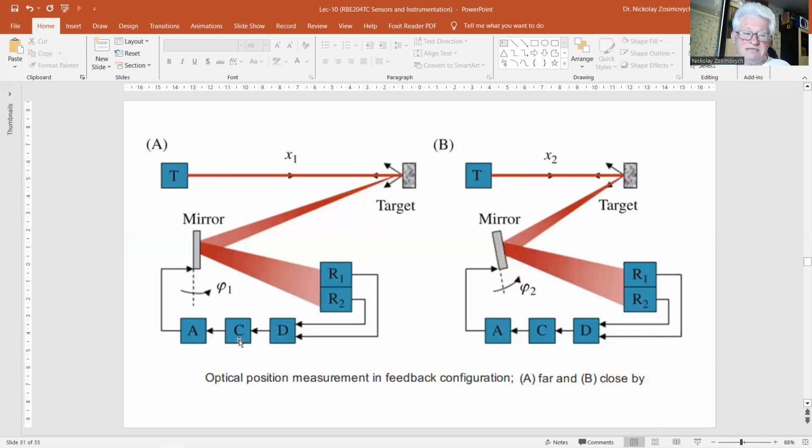To eliminate the influence of changes in source intensity and other unwanted interference in an optical displacement system based on intensity modulation, multiple sensing and feedback are effective solutions. Adding one or more receivers to compensate for the effect of the unwanted changes makes a reflection-based system less sensitive to the surface properties and may even allow uncalibrated operation.